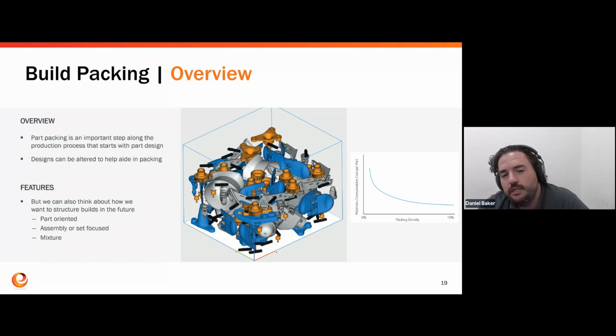The next major topic that we'll cover is build packing. As I mentioned, almost everything leads back to cost and efficiency as we're looking to do production scale. So focusing on build packing or nesting isn't something many designers think about today, but on the contract manufacturing side and in manufacturing in general, that's what's going to drive our throughput and our efficiency on the process. So there are a few options to consider when you're nesting parts.